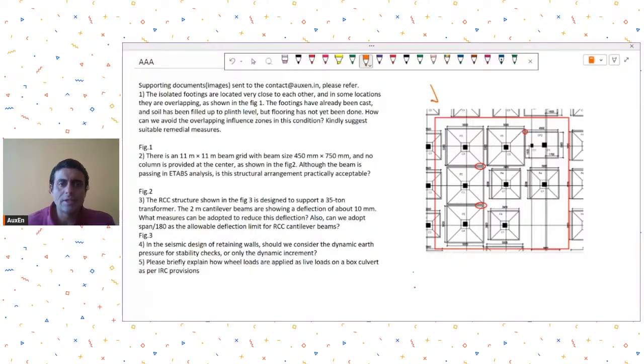This is not a very correct picture that I have drawn. The pressure bulb intensity is more just below the column. It depends on the type of footing also, but it is more below the column, and it gradually decreases as you move away from the column center.